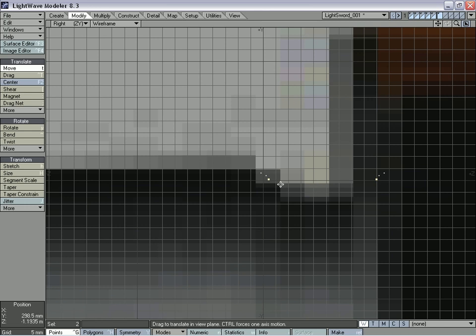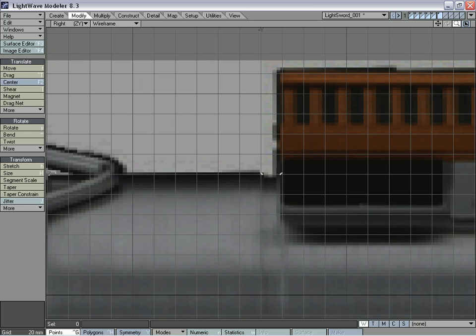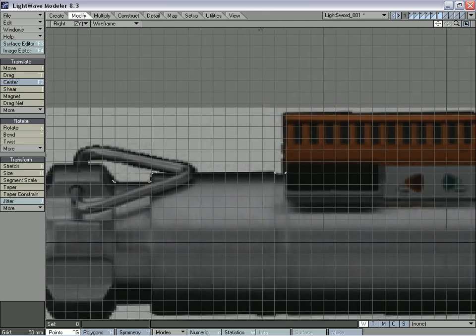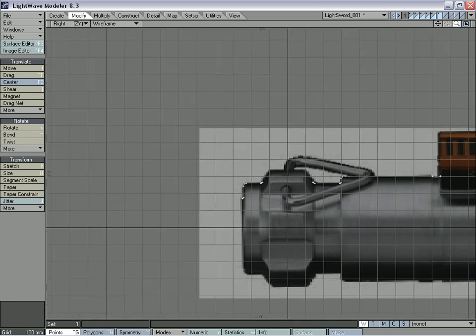And now we want a nice tight curve in here. Oops, undo that. So we're going to copy and paste it again. Use the stretch tool, pull it in, and T to move it down. And that will define a nice looking curve in there. And one last thing we need to do before we create the polygon is select these two endpoints.